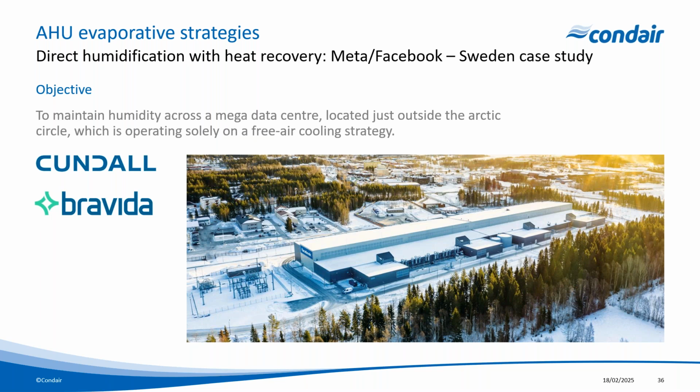So humidity control was a necessity here. And of course, with the massive air volumes, evaporative humidification with that preheat available, using hot aisle air from the data halls, was really an economic and efficient solution. Here we worked with Kundal, the consulting engineer, and Bravida, the contractor, to supply the evaporative cooling systems for this project.